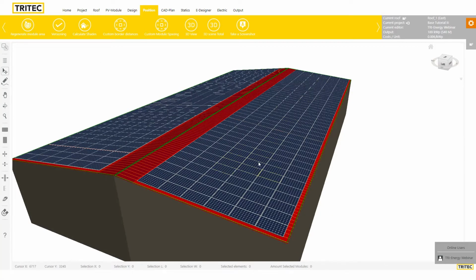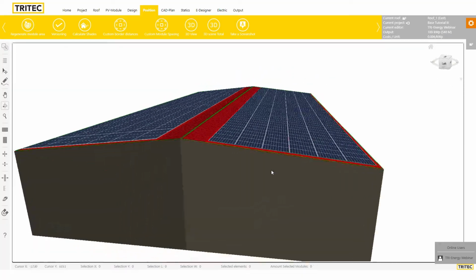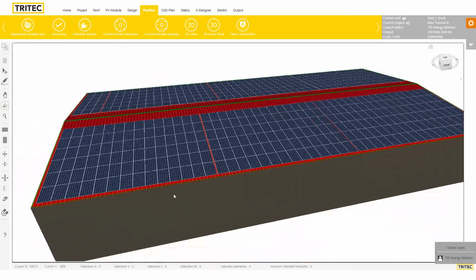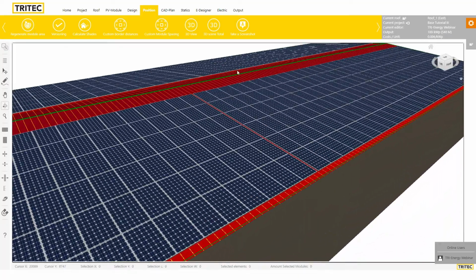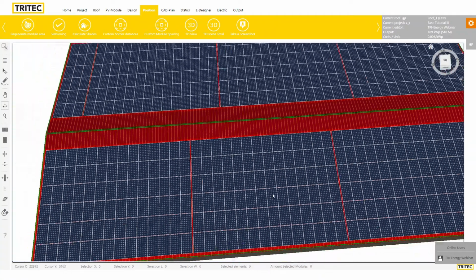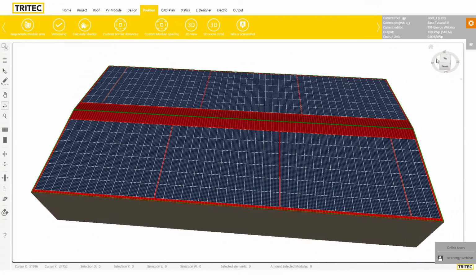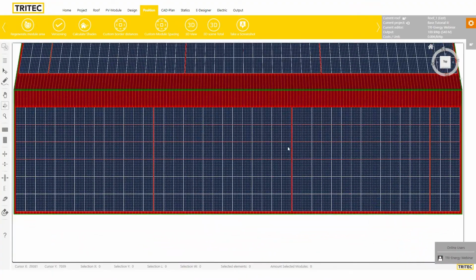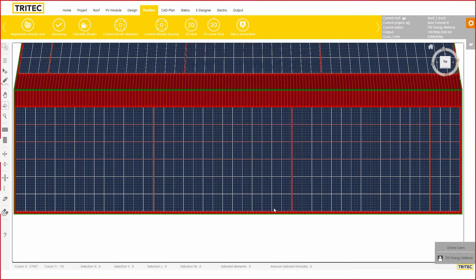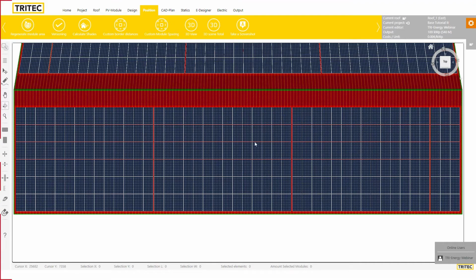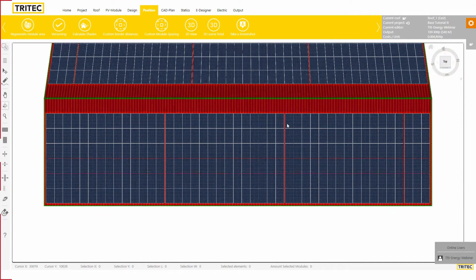Maybe you use that tool and you tilt it and rotate it, and you say, well, but I would like to go back into this original view where it's totally top. You could try to do it like that. The easiest way is just click on the house, and then we try to do the zooming so that the roof area is displayed and it's totally flat on the roof, so there's no perspective.